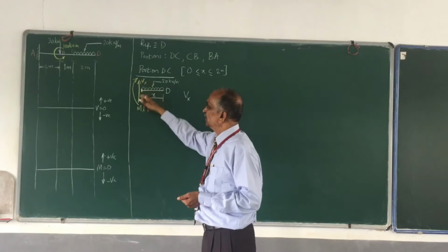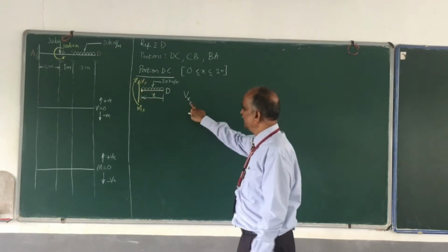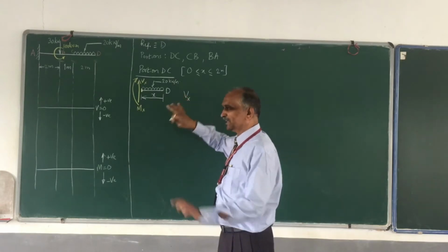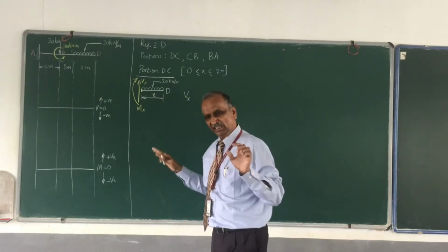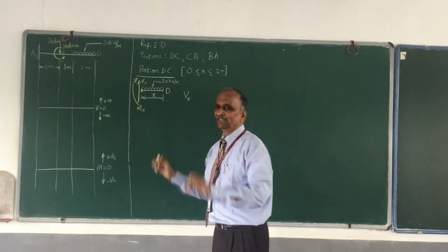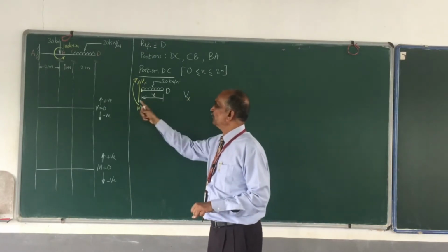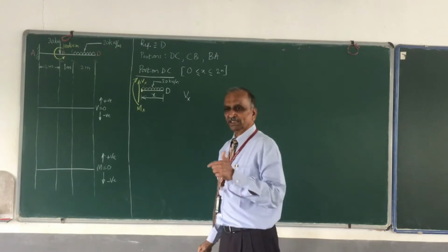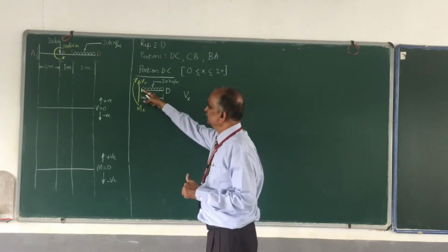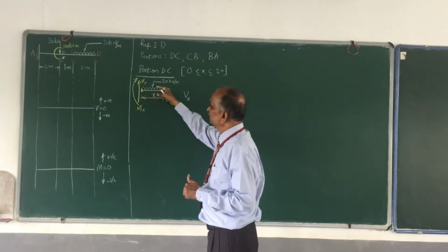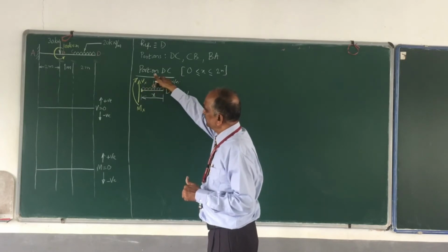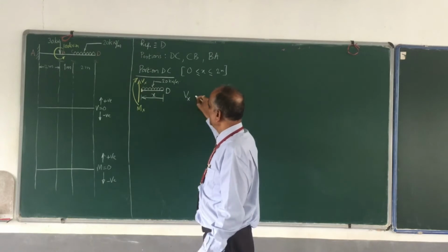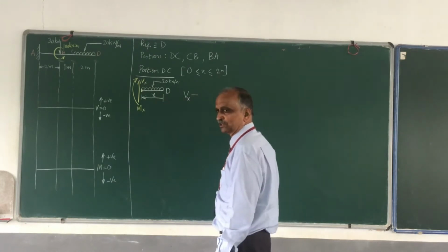Let me start with Vx. I have written Vx with a plus sign, with an assumption that unknowingly I have already made a sign convention. This upward shear force is positive, so any force in the downward direction is negative. So I have a uniformly distributed load, and the meaning of this is this load is acting in the downward direction. That means the force is downwards.